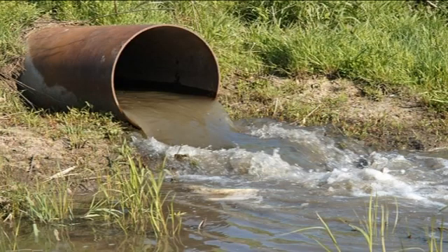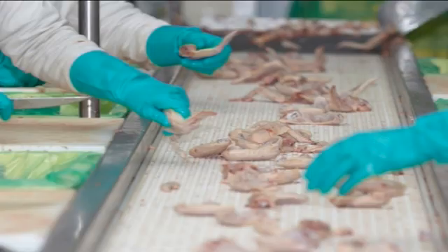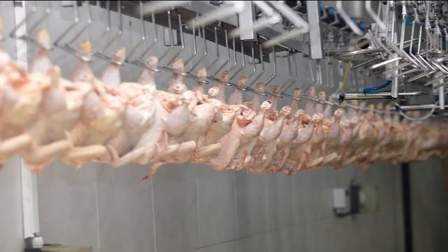Wastewater pollution levels depend on the kind of raw material being processed, on the plant technology, and the amount of wastewater generated is also an important factor, as the concentration of pollutants is inversely proportional to it. The general characteristics of the wastewater generated from different food industries are as follows. For example, in the meat and poultry industry, the wastewater generated from slaughterhouses and poultry processing will have a high organic load, and it may go up to 8,000 milligram per liter BOD. It also has a high concentration of oils and grease, salt, nitrogen and phosphorus, with suspended solids at 800 milligram per liter or more.